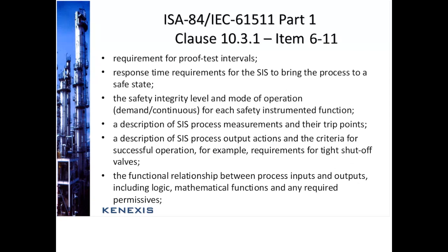We have the requirement for proof test intervals. Proof test intervals are determined when you do SIL verification calcs. A SIL verification calc will use a testing frequency to come up with the probability of failure on demand for the safety instrumented function. So that required proof test interval is going to be pulled out of the SIL verification calcs. Then the response time requirements for the SIS to bring the process to a safe state.